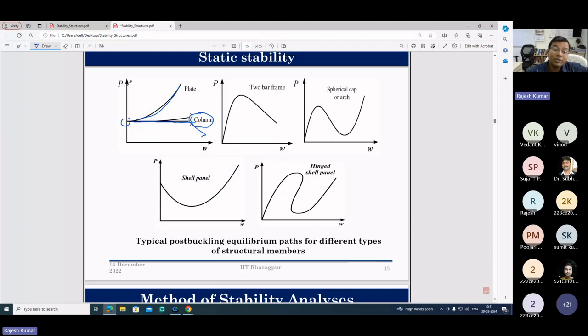And then if you want to examine the failure, for every deformation you find the stresses, and check whether the stresses cross the yield stress or not. Then at some places it will reach that, and now it becomes a collapse. So even at more than 3 to 4 times the load, your plate will completely fail. It does not fail exactly at the buckling load.